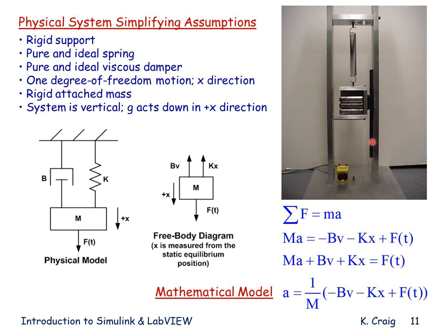So this linear bearing will have a combination of fluid damping and Coulomb friction, dry friction damping, which is nonlinear. Initially, in my first model, I will neglect the nonlinear Coulomb friction damping and treat the damping as being just viscous, linear viscous friction. So I treat this linear bearing as a pure and ideal viscous damper.